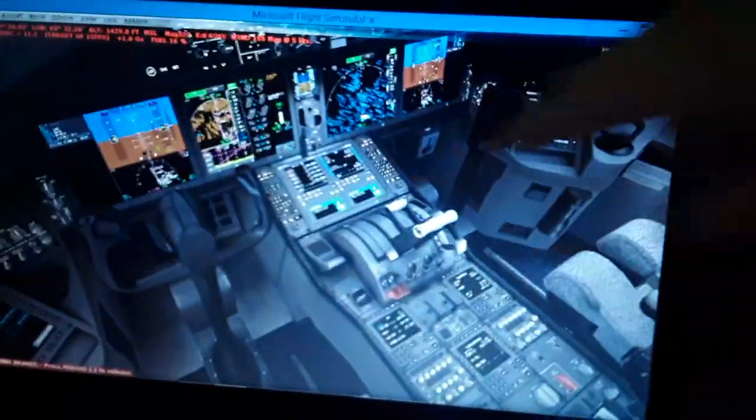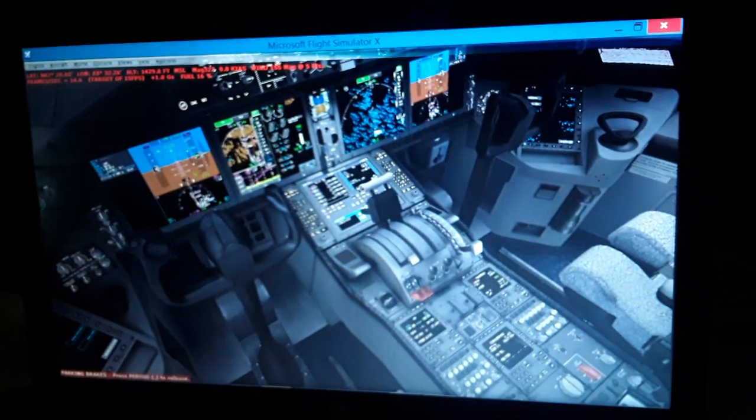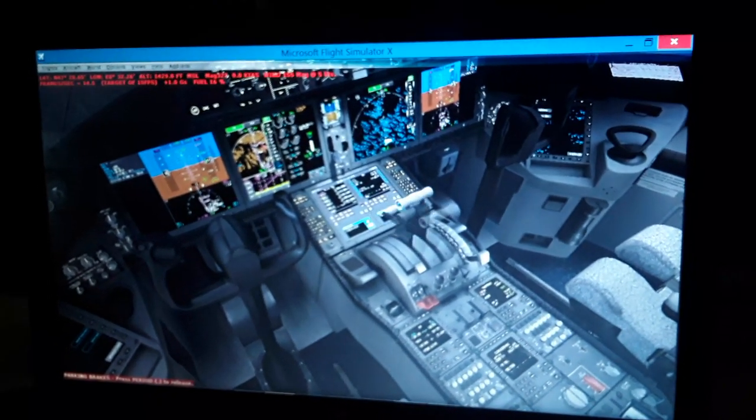We also have the heading guidance, the vertical rate of climb and descent of the aircraft in feet per minute, so the angles in degrees for climb and descent. Also the altitude select knob, the altitude hold switch, the localizer switch, and also the airspeed, which utilizes, as you know, the thrust produced from the engines. So it commands the engines. You command the engine's thrust rating when you select the airspeed guidance from the autopilot flight director system panel. You give a command to the engines.